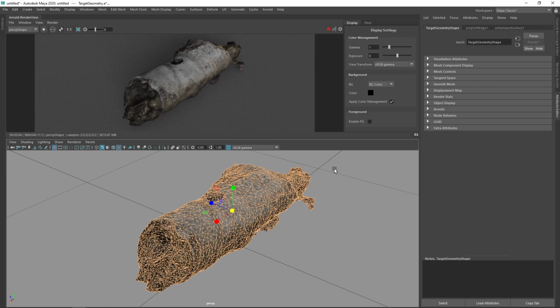So there's a really, really basic photogrammetry workflow for assets using Meshroom and Maya, and actually no other software. Getting that diffuse bake, if you need to bake all your diffuse textures to a single UV texture, you can actually do that all just inside of Maya.